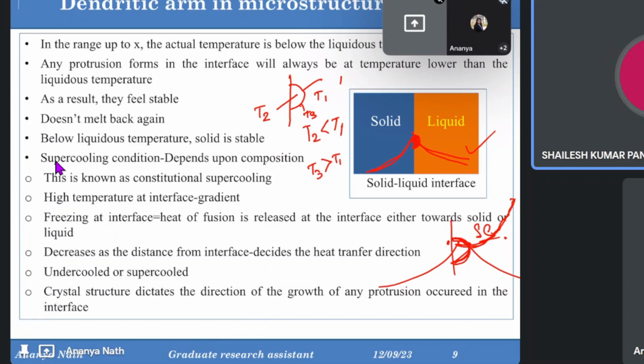So how can we relate this? More undercooling means we have more undercooling with high cooling rate. It's like that for high cooling rate, this thing doesn't really take place. This dendritic formation will take place, but the amount is very less. So for undercooling, as the delta G is high, there will be chances of having homogeneous nucleation. So the nucleus will form anyhow. It can form without any help of anything. It will form individually inside the melt, and this is how it's called undercooling.